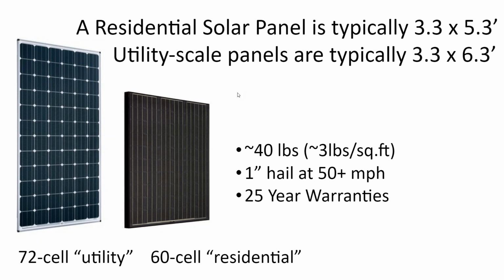When you're working on a solar panel on a rooftop, there is some give. You can lean on them. What you're supposed to do is try to put your weight on the frame rather than on the glass. But you can kind of Spider-Man across if you have to. Not that it's a good idea, but what I'm trying to say is they're more robust than weak.